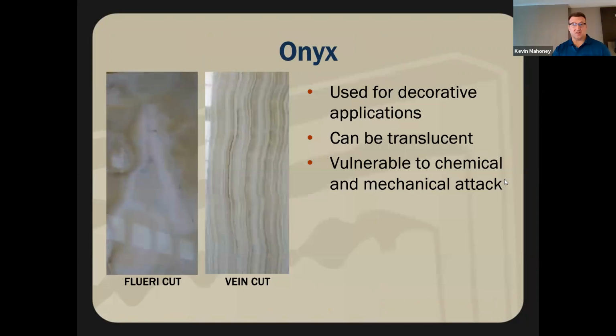Why we love this stone so much is that it's often used in hospitality and casinos, because after it's finished, it has this wonderful translucent feel to it that you can backlight. You can cut it very thin. You can use it for stair risers. Some of the things you don't want to use it for are on the floor. You don't want to use it in applications where it's going to get wear. It's not very durable if it's got direct wear on it.